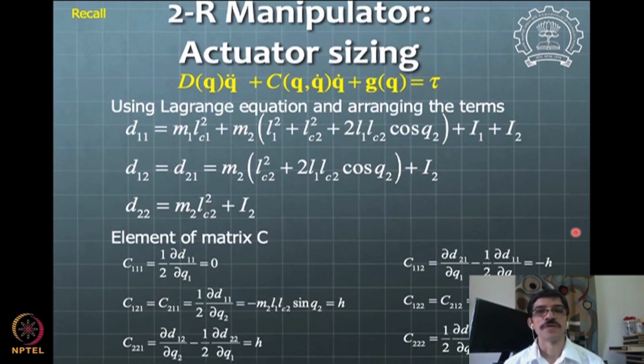And now these matrices or inertia terms are dependent upon q in general. So where you choose to move from that starting point PS, you will have a lot of possible variations in the D(q) matrix, and correspondingly in your estimates of the inertial torques.